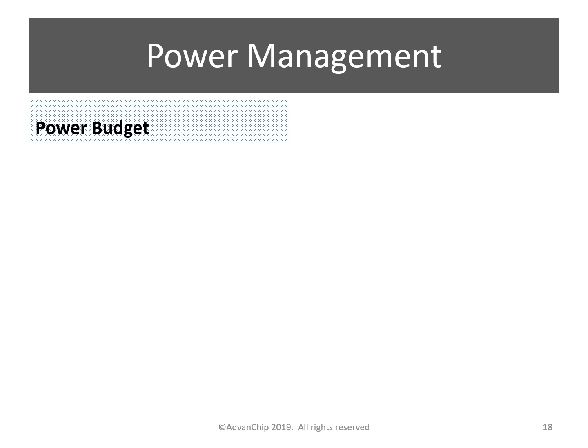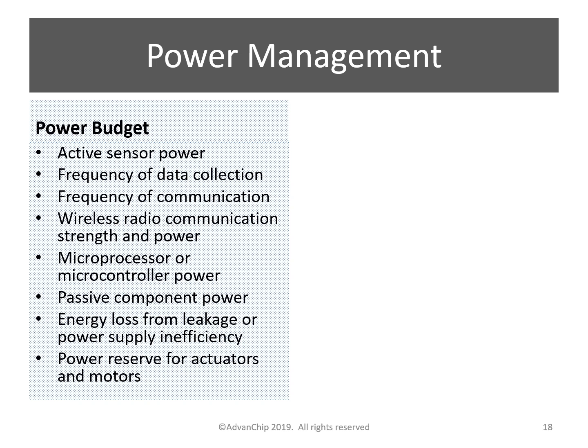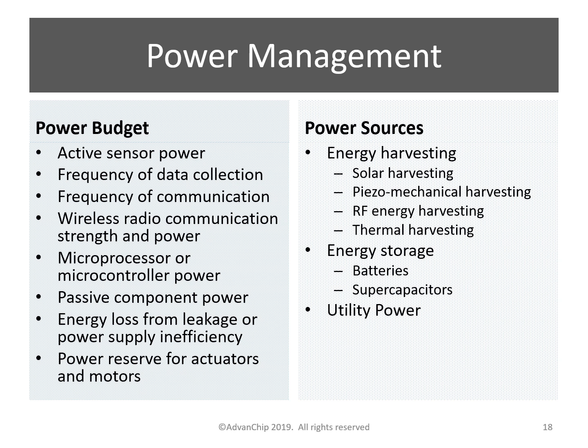Power management. Power consumption is one of the design considerations for IoT edge. The budget should add up all the components' power consumption, which should be less than the source of power. The power source, especially an energy harvesting system, should be chosen based on the edge power budget.